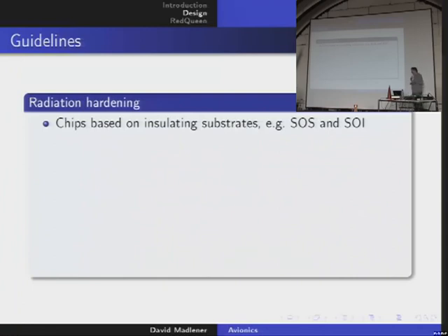And these chips are more resilient against radiation, because when an ionized particle goes through the chip, it produces a cascade of ion-electron pairs. And if they go through an insulator, this cascade of ions and electrons stays in the insulator, it cannot move. So it cannot flood the circuit that is built above the insulator. If the chip is made also of silicon substrate, then from the silicon semiconductor, these pairs will just swamp over to the circuit and maybe damage its operation.